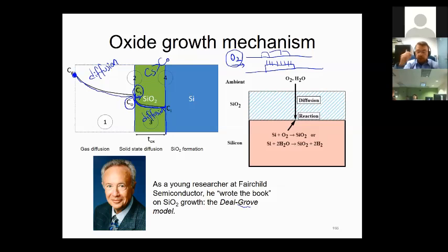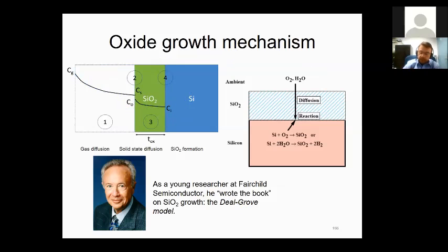So shortly, the oxidant should go through all these steps, should go down to the silicon layer to start the chemistry. As the fourth step, it goes down there and it reaches this concentration, and it starts breaking the silicon bonds. What does it do? It replaces them with oxygen. Okay, and then that's how the silicon dioxide is grown, from bottom to the up. All right. So that's showing you the two ways the silicon dioxide reacting with oxygen and water vapor.